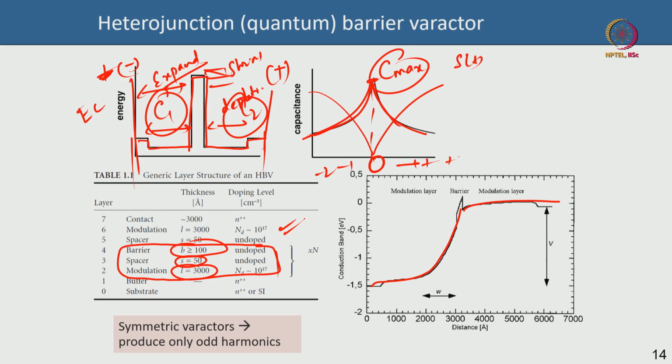So, you form ohmic contacts on both sides and you make this symmetric diode, and if you do the math, it so happens that this kind of symmetric varactor diode only produces odd harmonics, which is very good. In many applications you only need 3 omega or 5 omega, and this can fit the bill. Modern-day microelectronics heavily use more advanced forms of varactor diodes, Schottky multipliers, and you can easily get up to terahertz, more than 1 terahertz, at millimeter wave frequencies. You can do a frequency quintupler, 5 omega, and get up to terahertz for instance.